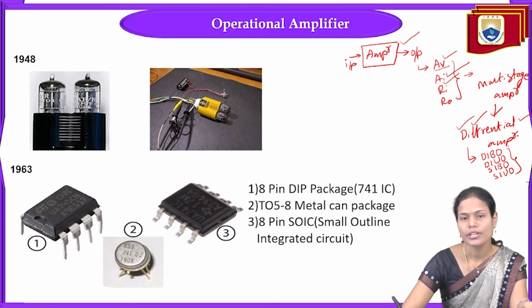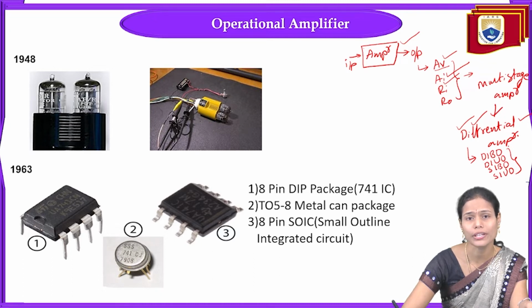So in each and every case of these differential amplifiers, we can improve the gain parameters as well as input-output impedances. Or else, if we interconnect these differential amplifiers to make a multi-stage amplifier, we can improve the voltage gain to a very high extent. That is the basic advantage of the differential amplifier, in any mode.